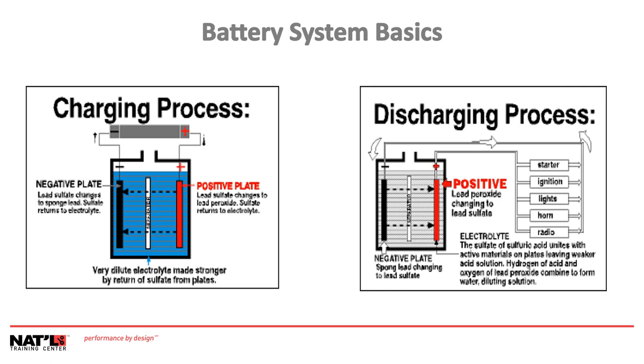It develops voltage from the chemical reaction produced when two unlike materials, such as the positive and negative plates, are immersed in electrolyte, a solution of sulfuric acid and water found in a typical lead-acid battery, for example. The voltage is approximately 2 volts per cell for a total of 12 volts in a typical car battery. Electricity flows from the battery as soon as there is a circuit between the positive and negative terminals. That happens when any load that needs electricity, such as the radio, is connected to the battery.